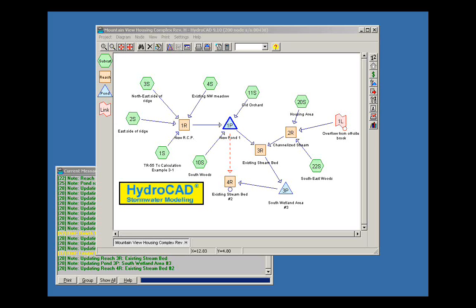If you were asking if they've already got Carlson Hydrology but an older version of HydroCAD, so they're HydroCAD users, but it's not 9.1, and they get the Carlson demo, what's the best way for them to get the 9.1 demo? Probably the easiest thing for them to do is to put a HydroCAD sampler on that system. That will replace the current HydroCAD installation, and then they would simply reinstall HydroCAD when they're done.